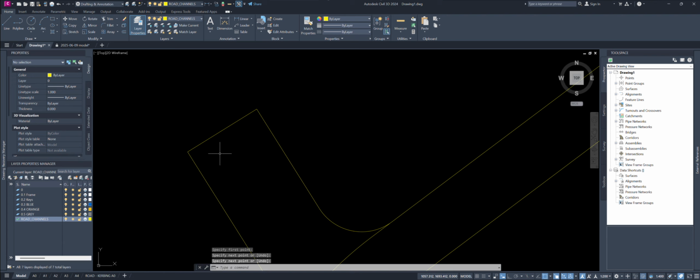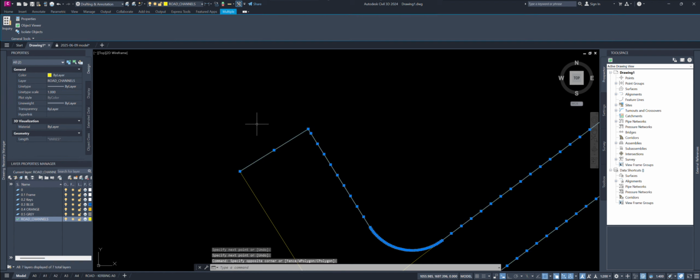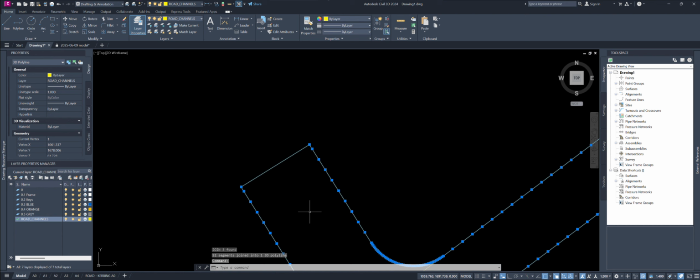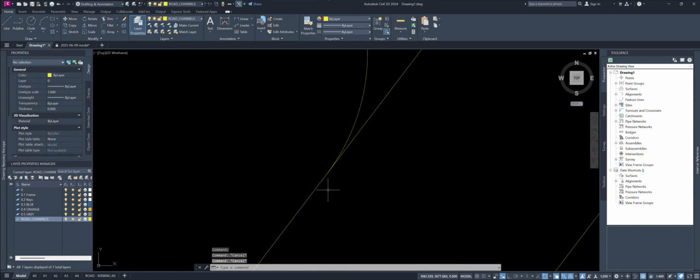It's really important to make sure you're not using a polyline but a line. Otherwise, it won't let you join them. So you can see now, again the same. We're going to type break. We're going to select the line.